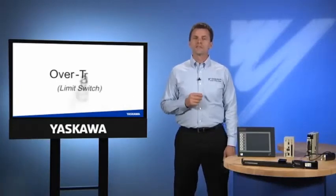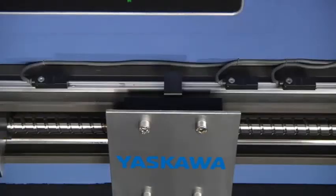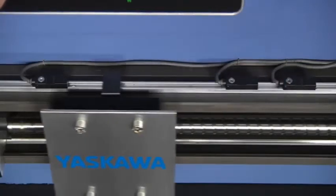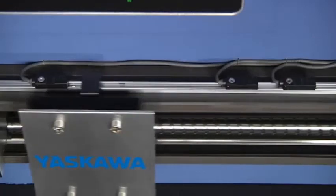Another direction-sensitive feature found in amplifiers is overtravel. Some people refer to this as the limit switch function. Overtravel is an amplifier input that stops the motor from moving in one direction. One input for forward and another input for reverse. We establish the boundaries of overtravel by placing a sensor at each end of the machine's range of motion. A properly programmed controller should prevent the machine from ever getting close enough to reach these sensors, but experience dictates the wisdom of planning for the unexpected.